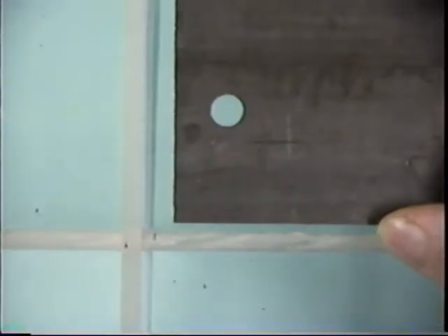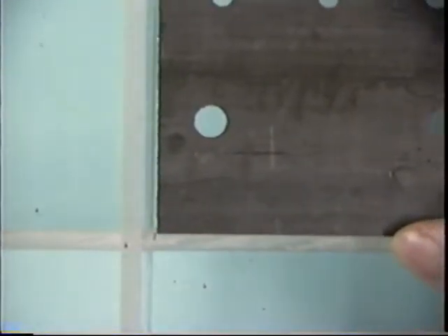Okay, this datum reference frame is not only in the visualization of an object, like we might use in geometry to define our CAD drawings, but we also use this datum reference frame when we work in our tooling and in our manufacturing. What I'm going to do is set a part here on the table, and we're going to locate this feature here with our part. And this feature, we're going to say, rests on a single plane, and this line right here represents a secondary datum, and then when we slide this over right here, this line would represent a tertiary datum.